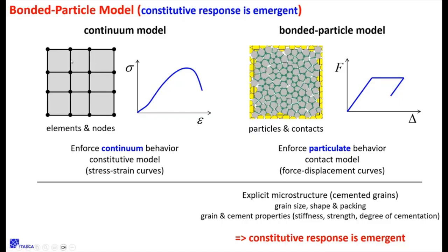there's not just 9, but a whole ton of these, and I'm squeezing it. And now let's say I just changed the system. I just pulled it. The element's not here. So now when I squeeze this, the force, the traction that used to go across here can't go anywhere. It's a free surface, so that force has to flow around, and this system will behave like a big giant square shaped excavation. Nothing there. I haven't done anything to the continuum model except remove an element, right? And if this was bigger, I could have removed a whole pile of elements that are all together, and then I have an opening in the mesh. We call this a mesh.